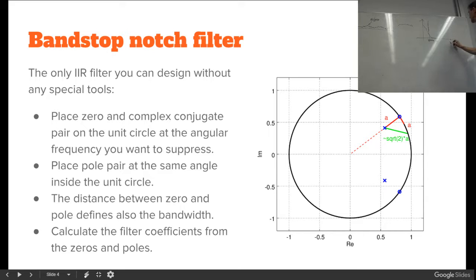Nyquist frequency. How to get rid of that one? One way would be to design an FIR filter which has a notch exactly at 100 Hertz.